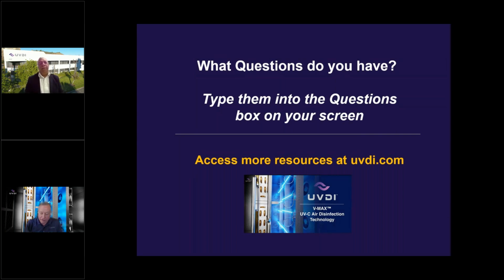All right, thanks, Ashish. Question on standards. Are there any current test standards in air purification? I can talk about, of course, for filtration, we have the ASHRAE 52.2 standard, which is for the MERV rating. For gaseous contaminants, there is a standard for in-duct, ASHRAE 145.2, to study the effectiveness of activated carbon-based technologies.